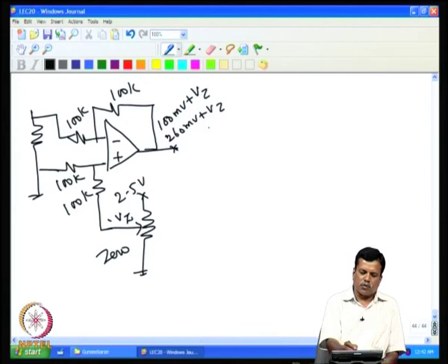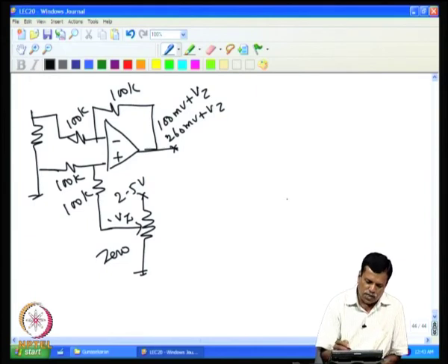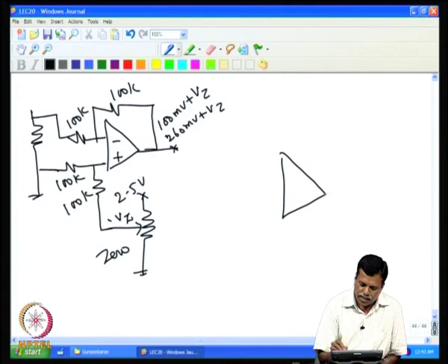As I said, the Vz needs to be added, so that one can easily design the next current converter stage. So, now we will go and design the current converter stage. For this, you take the operational amplifier, and this needs to drive the current. So, we can even have a Darlington pair for driving this.